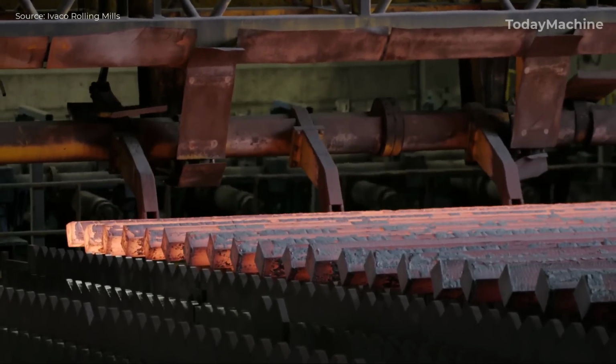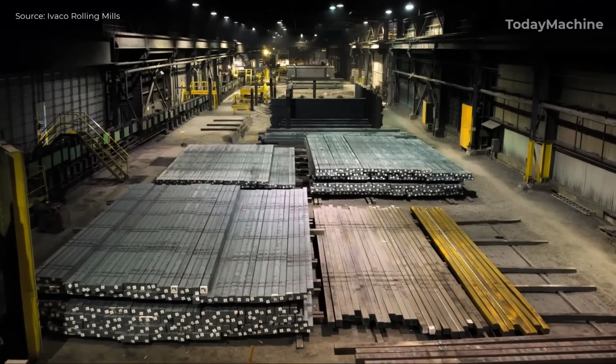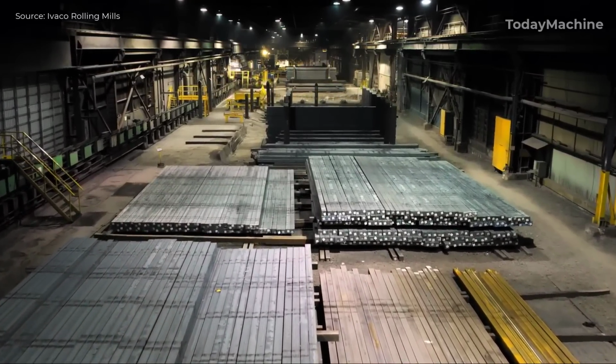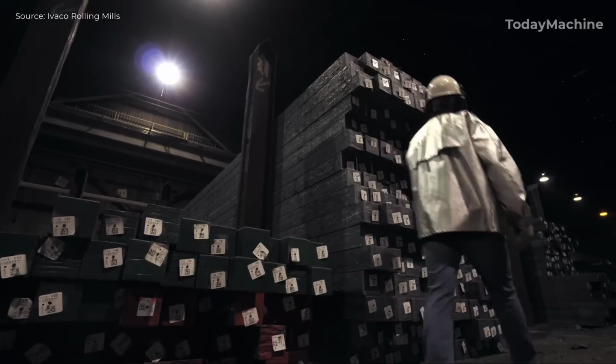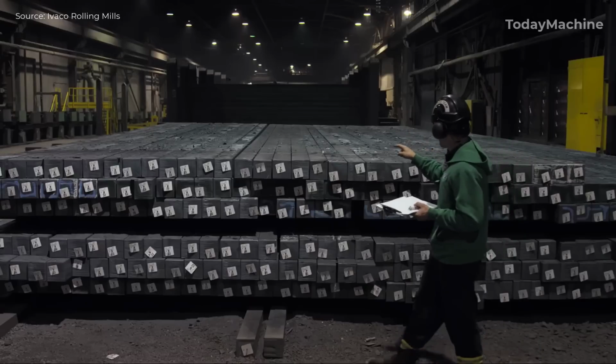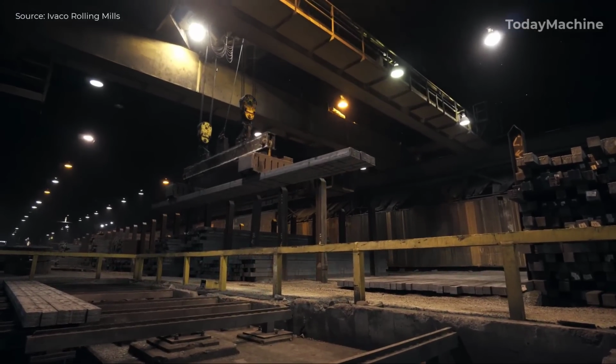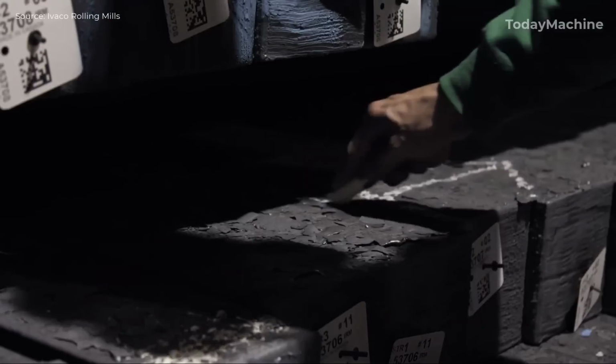Rolling mill operation. The billets, now solidified, are straightened and cut to length using oxygen torches. They are then assigned unique identification numbers for tracking and quality control. The billets are stored in an indoor yard, where they cool down before being transported to the rolling mill for further processing.